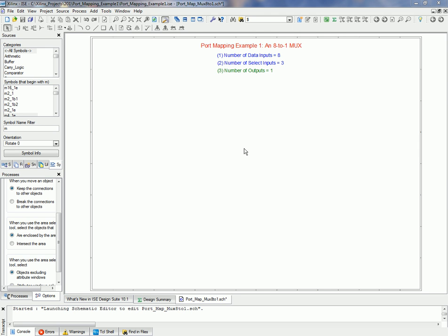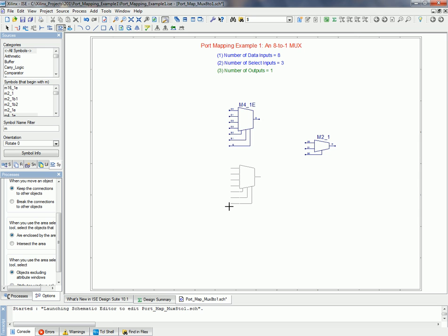The way I'm going to design this mux 8-to-1 is have a 2-to-1 mux in the back to select between 2 4-to-1 muxes that'll be in the front. As we've talked about in class, there is always one mux in the back that selects between the muxes that would be in the front.